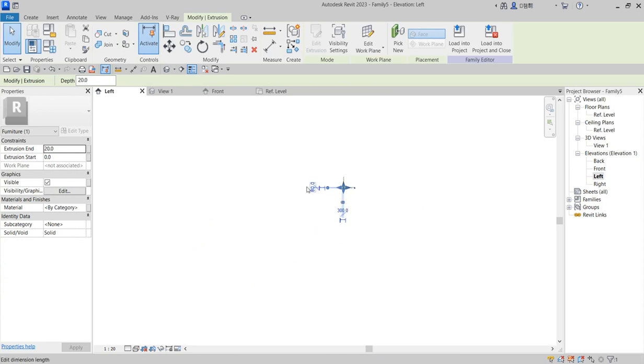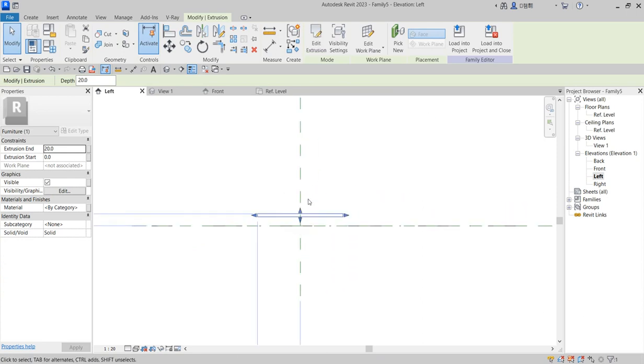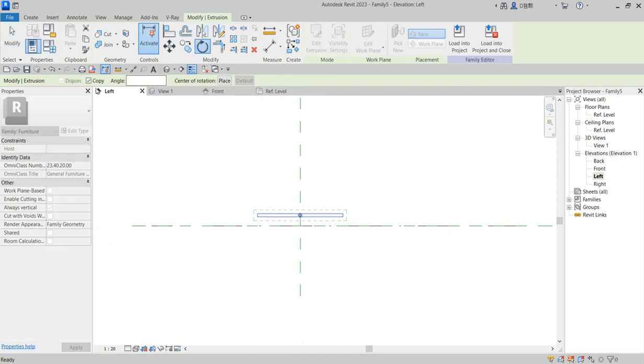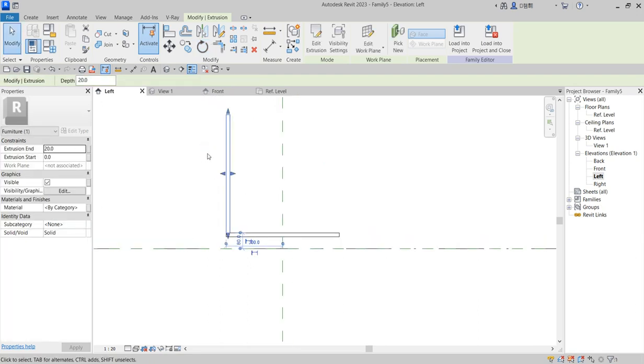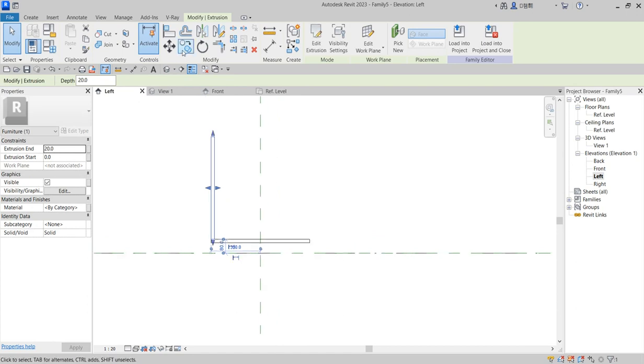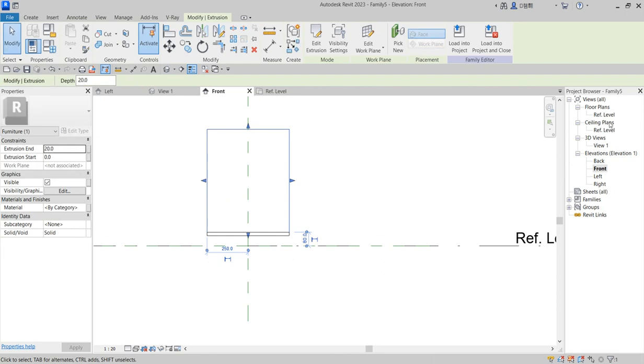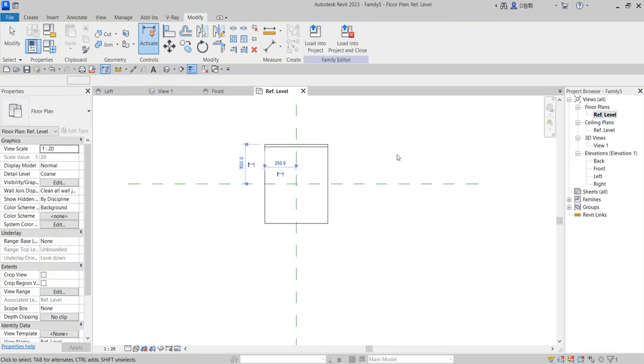So the first thing you want to work on is the drawer. So you click on this and click on copy, take this to the extreme parts, then rotate to 90 degrees. Fine. So as you have done this, which is beautiful, what you need to do now is to come back to your front, click on the top of this tab.